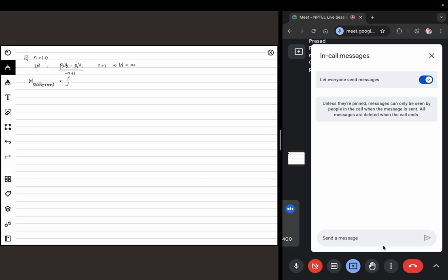Again we use the same equation, integral PdV, but now it will be C by V. Previously it was C by V to the power n, where n equals 1 in this particular case, between the limits V1 to V2. So this leaves us C times ln V2 by V1. So what is this C? As we have said, C is P1 V1 or P2 V2, whichever you take, times ln V2 by V1.